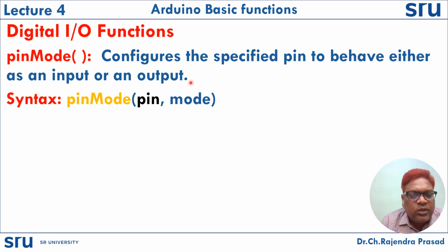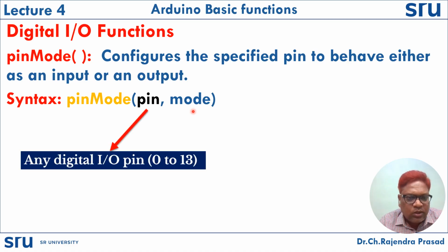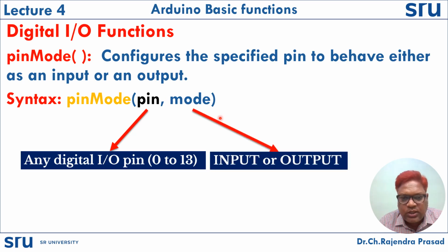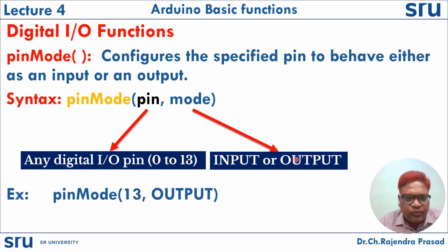Then the syntax for this function is pinMode(pin, mode), where pin represents any digital I/O pin, numbered from 0 to 13, and mode represents either INPUT or OUTPUT.